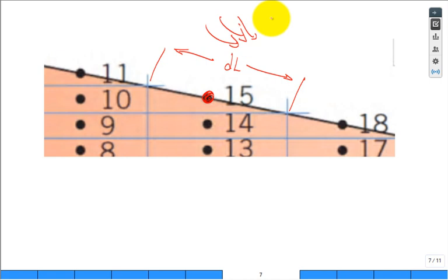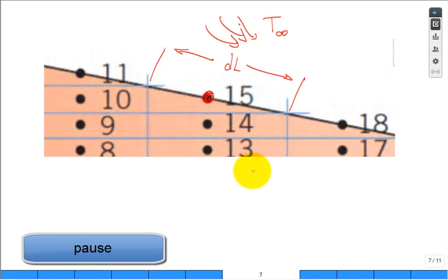Yeah, and that fluid temperature is T infinity. Can you write an energy balance equation for node 15, and all of the rates of heat transfer, you write them as going into node 15, just like we did it going into node 9. How many conductive pathways do we have? And then we have the convective.